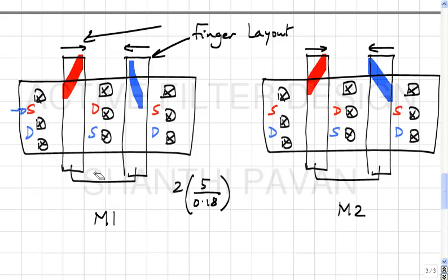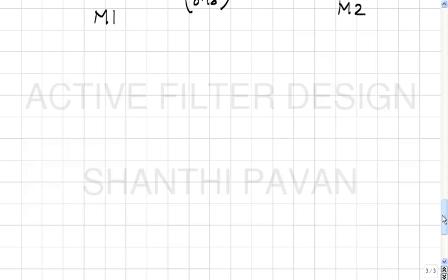The drain capacitance is proportional to the area occupied by the drain. So choosing an even number of fingers and choosing this style, where the drain is shared between the fingers, results in the least possible parasitic capacitance. Does it make sense? Which is why this finger type design is also what is commonly indicated on schematics, right?